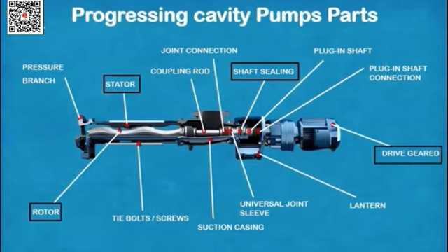The stator of the pump is designed and built in a single block design. It is composed of a steel shell, which has a double helix profile inside made of rubber. The main elastomer types used in stator manufacturing are nitrile butadiene rubber, ethylene propylene diene monomer rubber, fluorocarbon and polytetrafluoroethylene, which are chosen in function of the abrasive media, chemically aggressive fluids and various working temperatures.